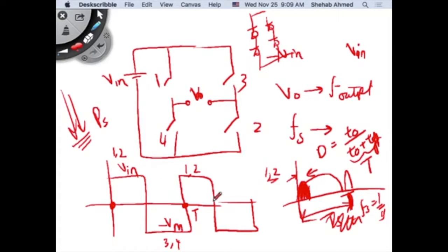The alternative to this is to figure out a way to improve the harmonics. If you want to create a nice sine wave, it's not going to be by switching at fundamental frequency anymore. You have to switch faster to be able to chop up this waveform so that it resembles a waveform with less harmonic content.